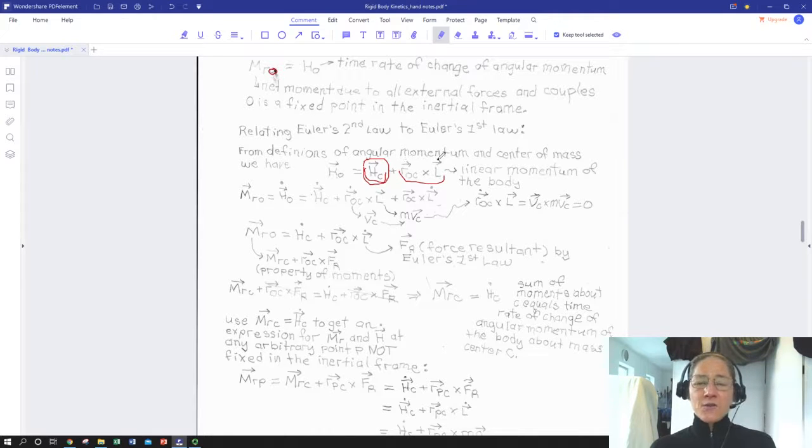Then we've got another expression which is basically the equivalent to the time integral of r cross F, which is more a point force application. So we've got a rigid body part of our total angular momentum, and then we've got something that could be related to that same body acting at its center of mass like a particle. So we've divided our angular momentum into those two sections.